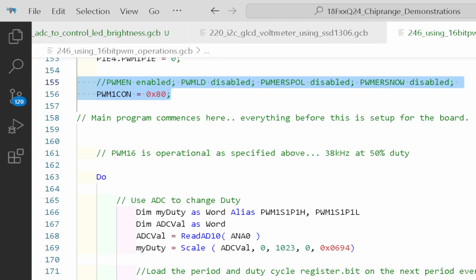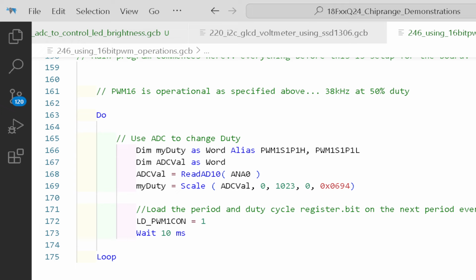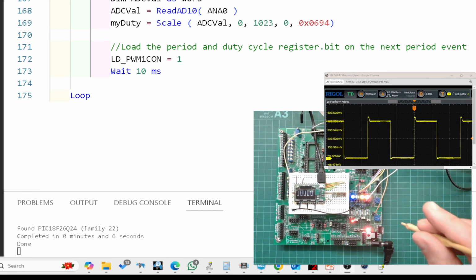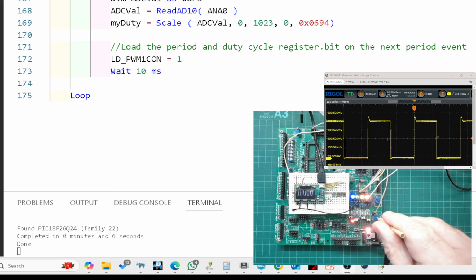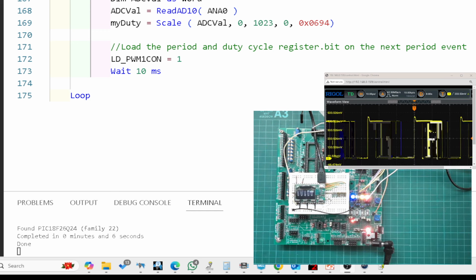And that's it. So you can actually use GCBASIC to write direct to registers. There is no trickery going on here. It is writing direct to the registers, and you're controlling the registers without any complexity or trickery by the compiler. You can write direct by using byte variables, aliases, longs, words, use whatever you like. I don't care. It works. Because we can see it working over here. We're right into those registers. I'm changing that value. Fantastic. Works a treat. You can now know why I've got two oscilloscopes. The Rigol web client doesn't work that well.